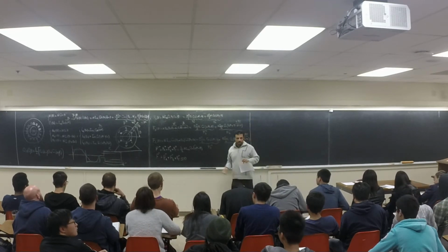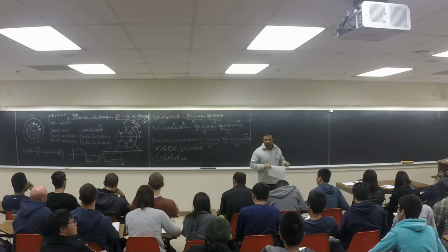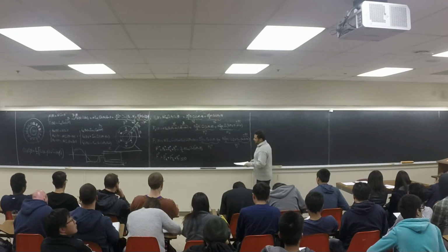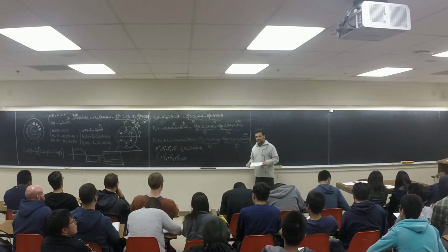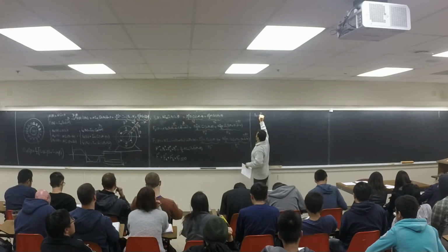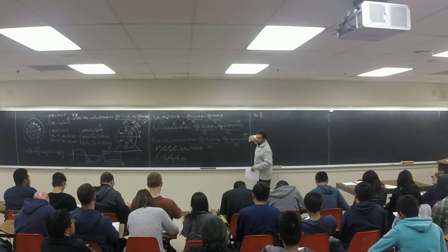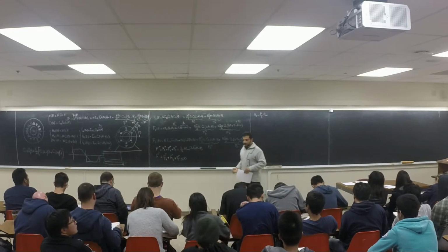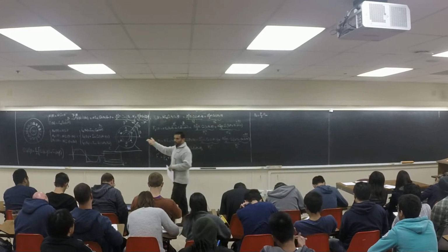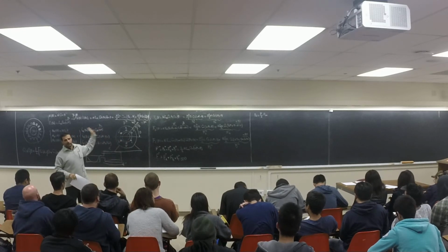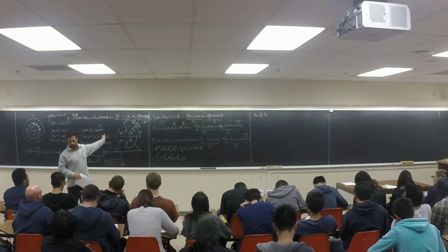Any question here? Now, the same equation we had for the DC machine we have here. Theta electrical is equal to what? P over 2 times theta mechanical, right? Here again is a two-pole machine. The one I showed here is a two-pole machine, but you can design it to have as many poles as you want.